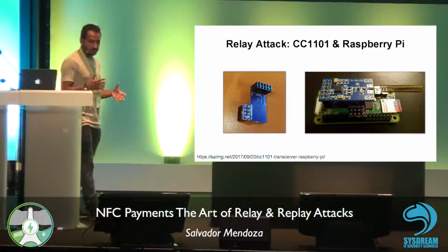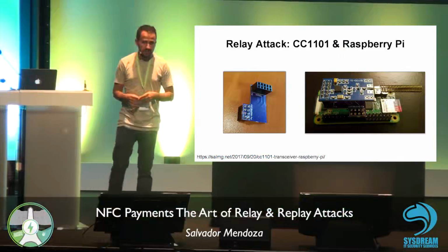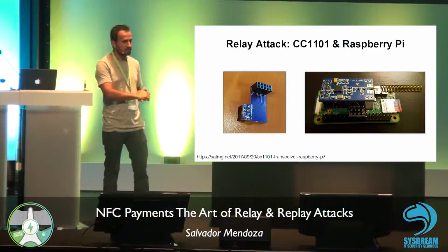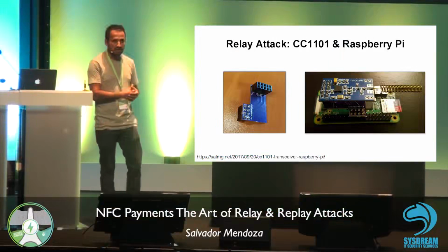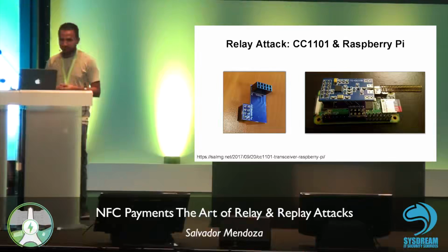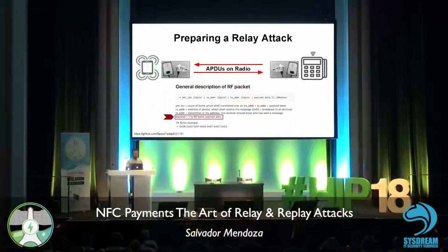There are many cables, so I designed a PCB where you connect the CC1101 to the top, and you put it on the Raspberry GPIO without any issues. Another limitation of the library is that the payload to send a packet between the two devices has a 60 byte limit.